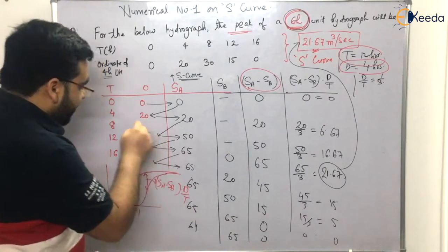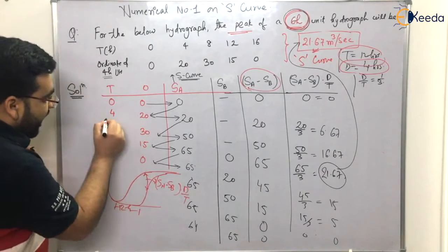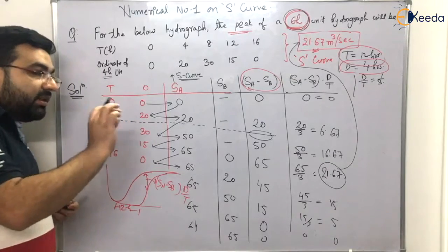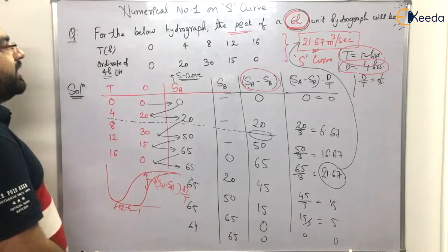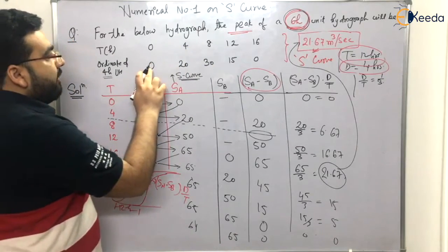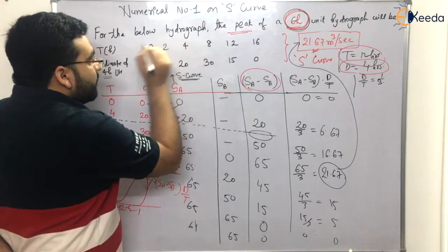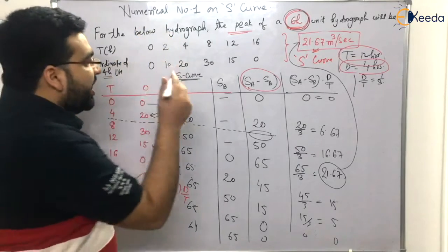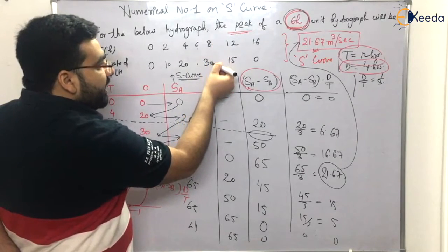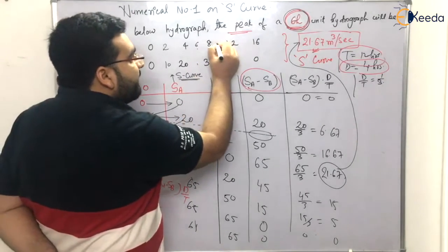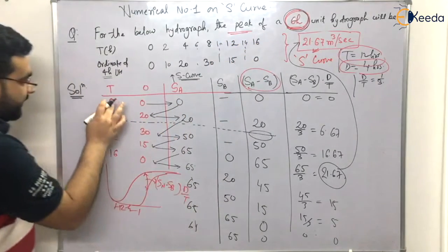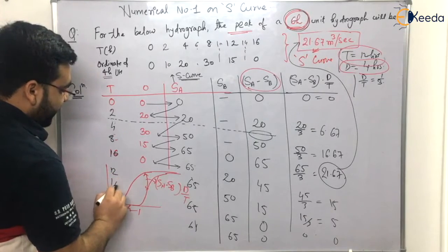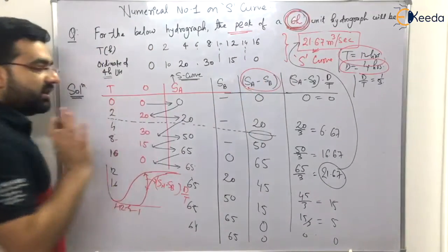So how can you lag it by 6 hours? Because here you have 4, here you have 8, so 6 hours will be somewhere here. But I don't know the value at 6 hours. At that time, what we do is we break this 4 into smaller parts. Let us say from 0 to 20 it is 4, then I also take 2, take the average of this, it is 10, right? It is 4 to 8. Now 4 is 20, 8 is 30. Then I will see how much the incremental change is, and for 6 also I calculate the value. Then for 8 it is 30, for 12 it is 15. I get the incremental value and I get the value of 10 also, and similarly 14 also, right? So I will draw this table for 0, 2, 4, 8, 10, 12, 16 and so on. And that is how I can shift it with a 6-hour duration.